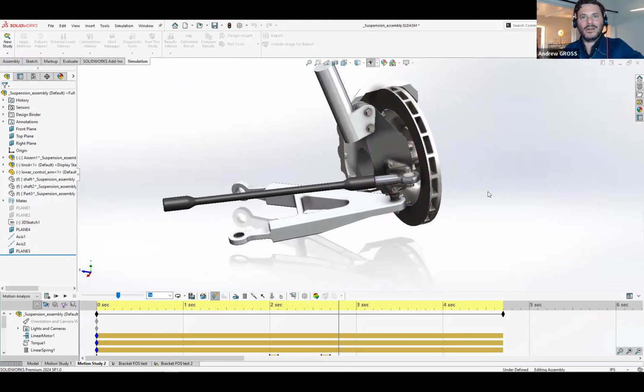Now, you can fudge the system a little bit, right? We can create contact between groups and understand some elastic properties. Say if two parts collide in motion, maybe I understand the coefficient of restitution between them. That would estimate, say, rubber or steel or plastic, but nothing's going to actually deform here.